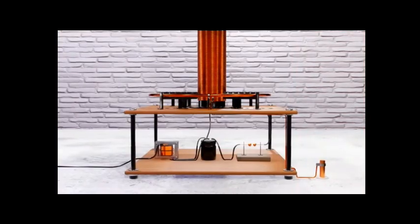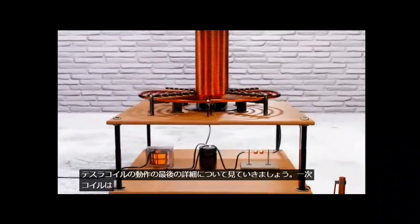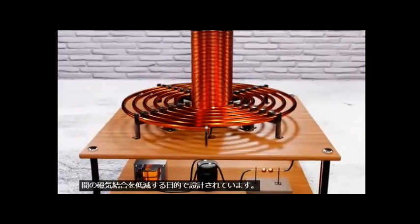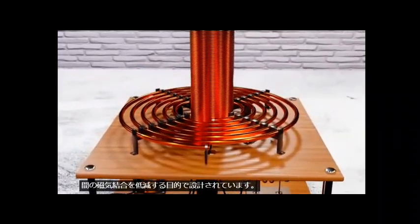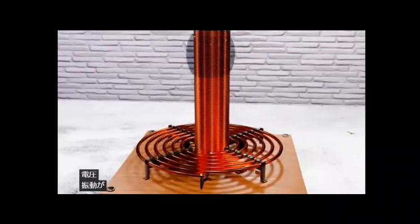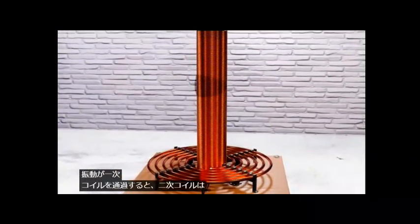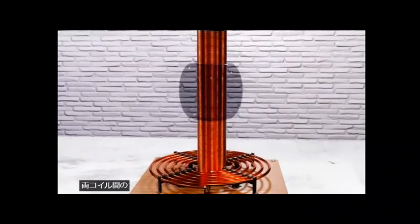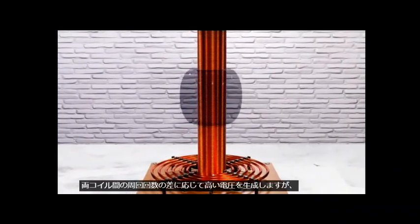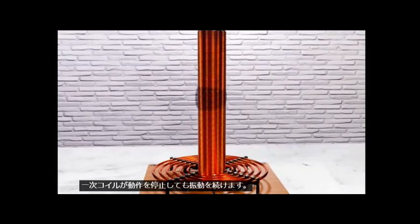The last detail of the operation of a Tesla coil is in the form of the primary coil, which is designed with the aim of reducing the magnetic coupling between both coils. In practical terms, this means that when a voltage oscillation goes through the primary coil, the secondary coil will generate a higher voltage for the difference in the number of laps between both coils. But it will also continue to oscillate, even if the primary coil stopped working.